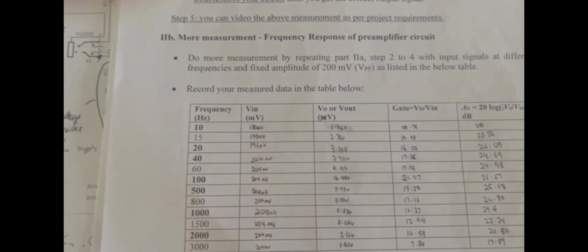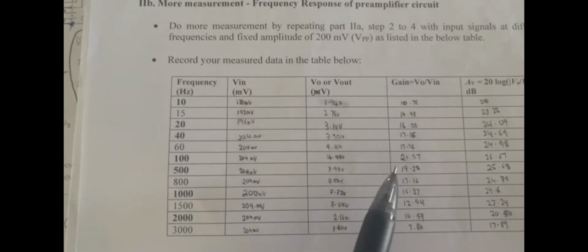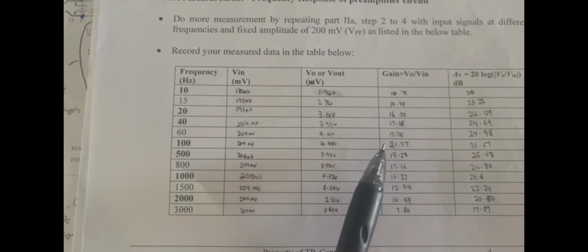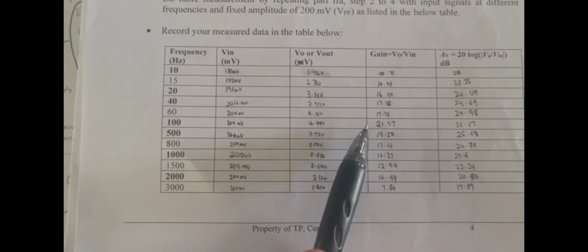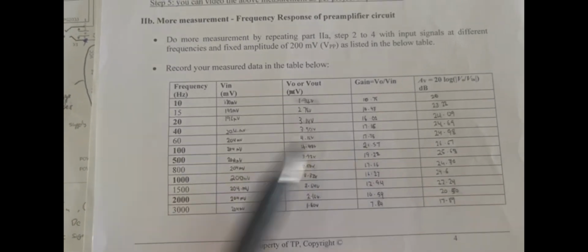So the passband gain is 1 plus R2 over R3, which is equal to 1 plus 220k ohms over 10k ohms, which will give us 23. So the passband gain is 23. From there, we can pull out our measurements, and we can see my maximum measurement for our higher gain is 21.57, which is close to our calculated passband gain.